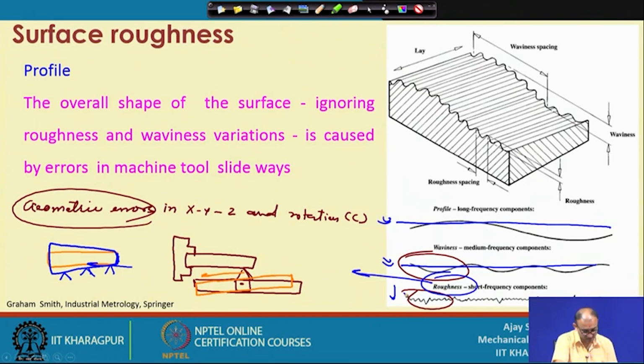It is very random in this case, that you are not able to control. So, you will not get a straight line of the roughness. If you increase the magnification of any surface at a small scale, then you will get the roughness profile anyhow, because it is almost impossible to get the surface roughness in a straight line. But we consider this a perfect surface if it is fulfilling our requirement,